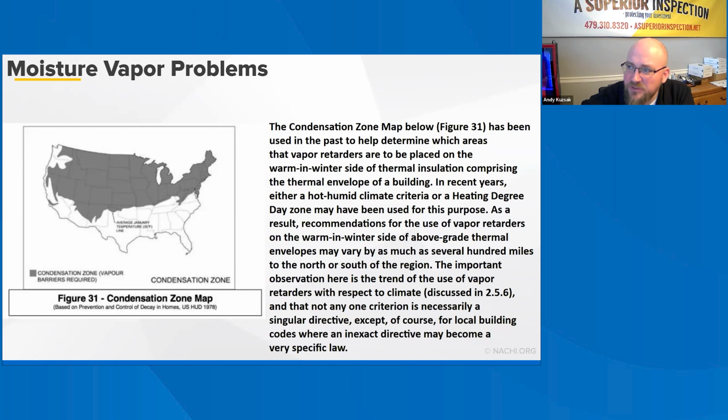One option is the continuous fan operation at a low level with local switches that can boost the fan speed temporarily. In humid regions, the addition of damp outdoor air without any treatment of this new moisture load will actually add moisture to the house instead of helping to control indoor relative humidity. Heating, cooling, and ventilation systems in such climates should be operated to accommodate additional moisture loads resulting from ventilation.